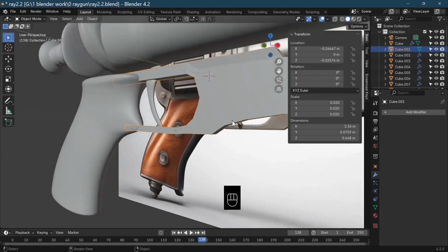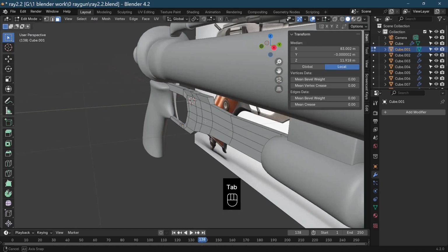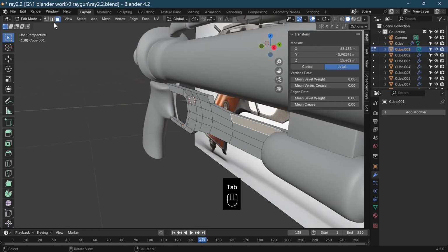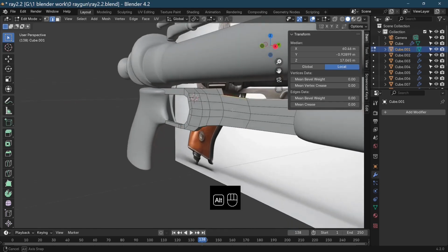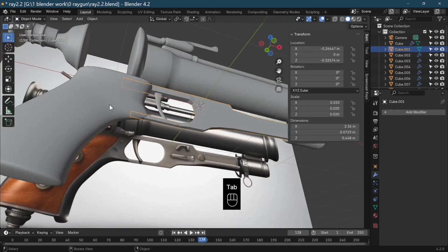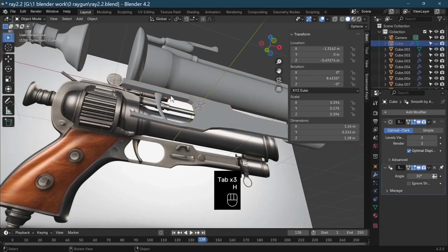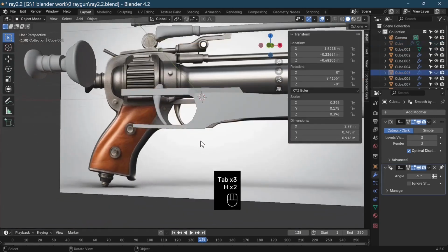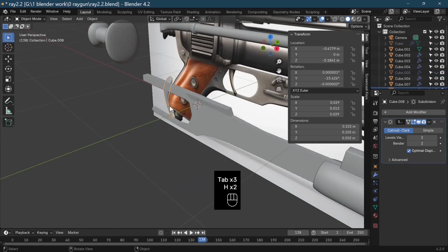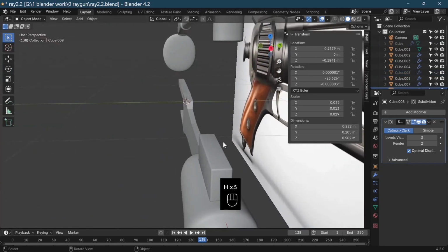Now, because these are flat-edged items here, what I like to do is add a bevel to the outside of these. So I'm just going to select the outside, like that, and selecting the edge all the way around. But these other items are making this a bit hard to see, so we use a special key called the hide key. And we can hide the things that we don't want to interfere with our model.